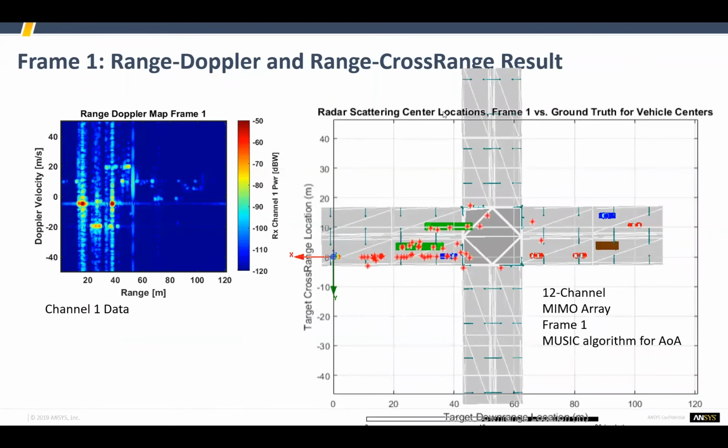and it lets you do things like this, where we can look at radar scattering center locations for each frame, right, versus ground. That will then produce the plot on the left, where we very clearly can see the main scattering centers that look like our 18-wheeler trucks, but it can also showcase or highlight other cars that are at different ranges, and even the return echoes from the light poles, etc.